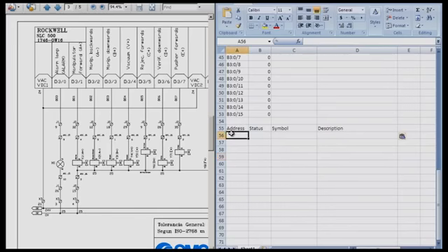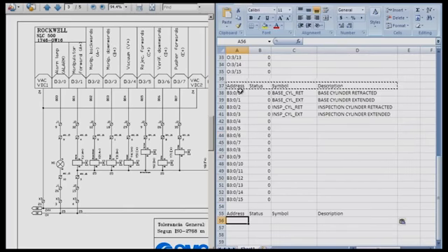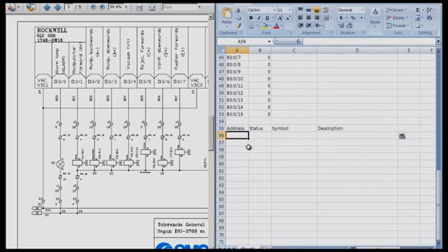And those are going to be used as internal bits in our PLC program. So again, now I used B3:0 in the previous addressing of our cylinder positions. So now I'm going to use B3:1 because it's the next available word in the series. So B3:1/0, and I hit enter.